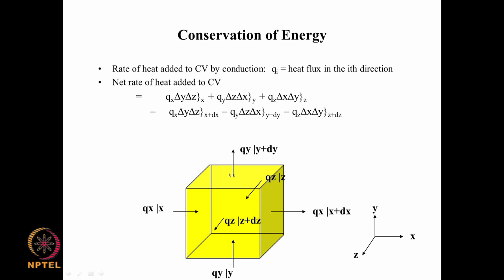So, this is a minuscule control volume, it has no walls; these are bounding surfaces, and this is part of the fluid domain. You have a next cell here, and between these two there is a wall. Okay, there is a wall which is made up of the fluid itself, it is not like a physical wall which is separating the two. So, depending on the temperature here and the temperature here, if the temperature here is more than the temperature here, then heat would come in through this way and Qx would be negative.